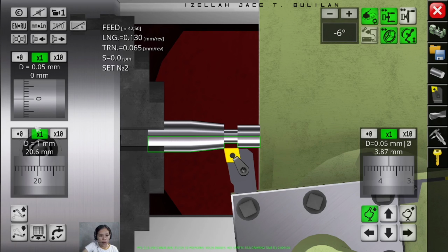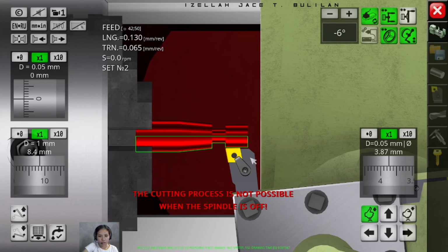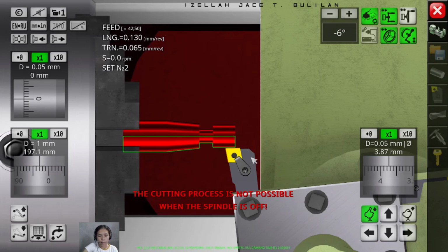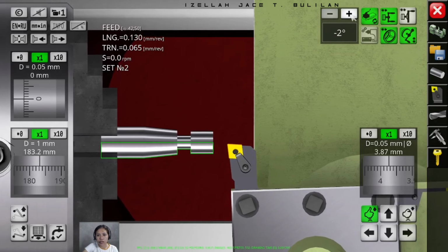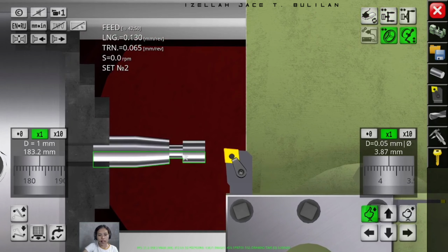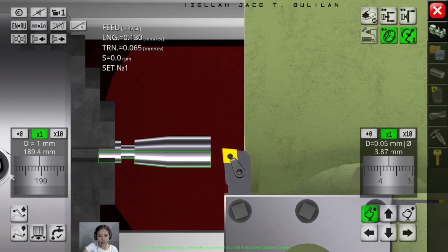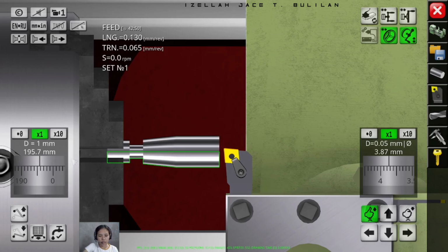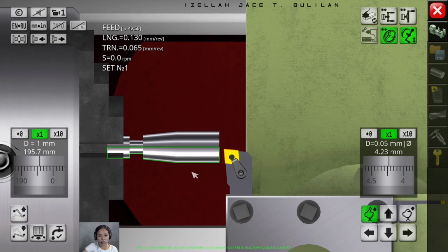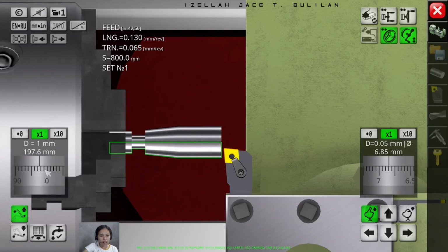Now we're just going to move our cutting tool further away from our workpiece and set back the angle to 0, because the last step is we're going to do the facing operation, reducing our workpiece material by 18 millimeters to achieve a total length of 82 millimeter. So to do that, let us first calibrate.